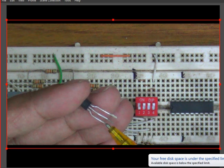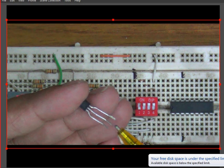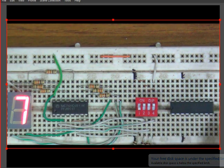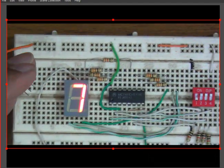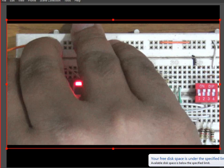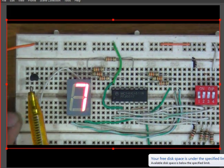E, B, C. I'm again repeating, this is pin number 1, pin number 2, pin number 3. So now when I'm going to use it on this breadboard, supposedly I am going to use it over here like this. I have placed it over here like this. So what was the flat side? I have the flat side over here.